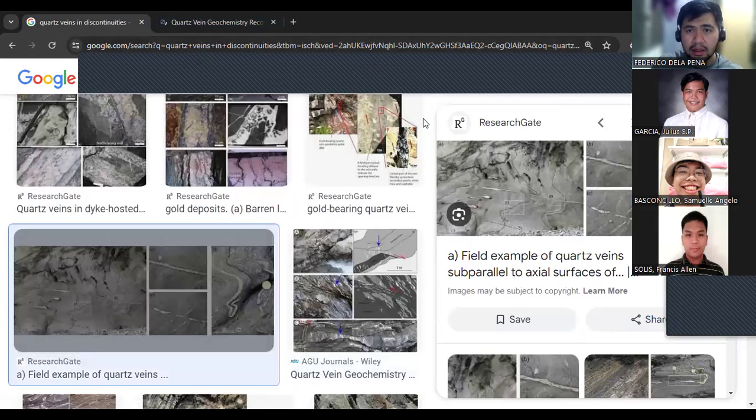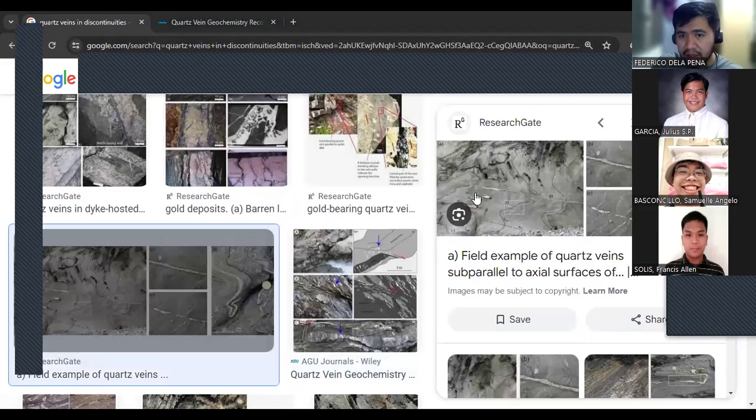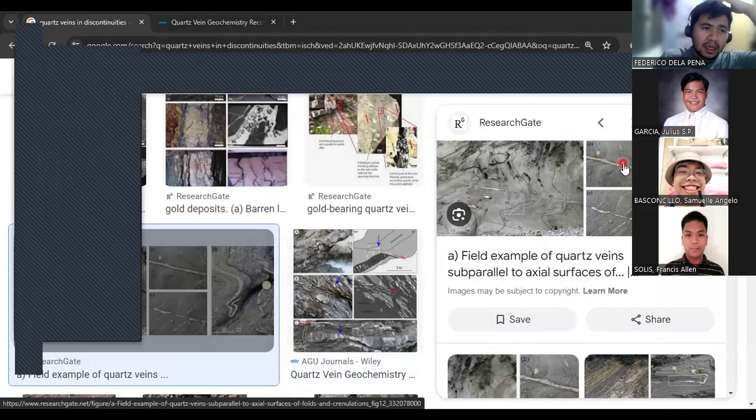This one. All right. You can see in this photo, you have a solid rock and you have white lines. These are your quartz veins, or if you are an engineering geologist, these are quartz cement and discontinuities. And they can actually strengthen the rock. Okay? Rocks with quartz or calcite cement in their discontinuities can be stronger than a rock without any discontinuities at all.